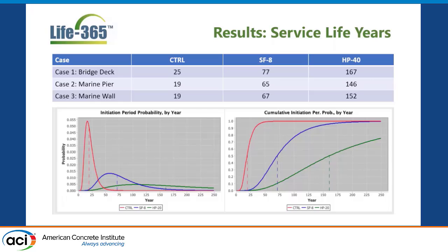Everything I've said so far is the first estimate. I may have fat-fingered a value in the wrong place somewhere. I may not have thought correctly about what kind of structure this is and what the splash is. This is the first of probably 100 iterations that you do, where you just keep changing values and look to see what effect it has, such as the change in the depth of reinforcing. One of the cheapest ways to get service life is just to increase the depth of the reinforcing. It buys you a lot, but maybe it's just not reasonable from a design or a delivery standpoint.